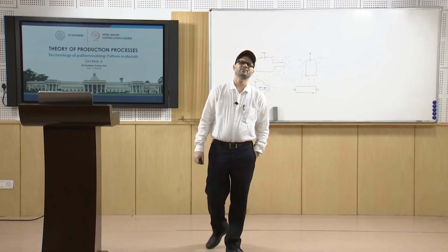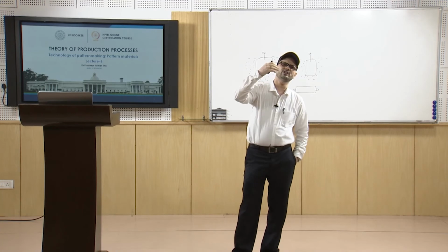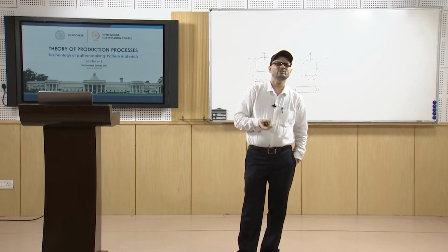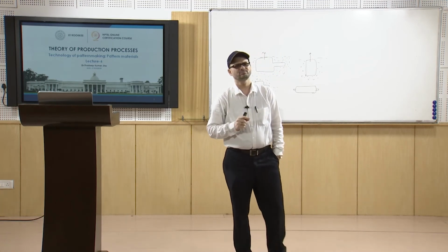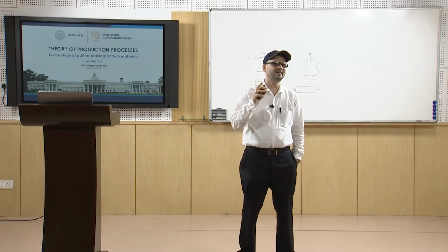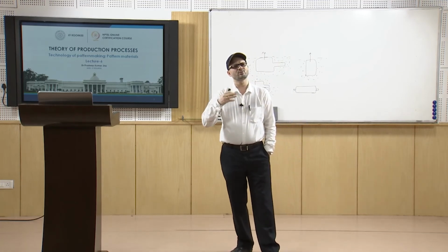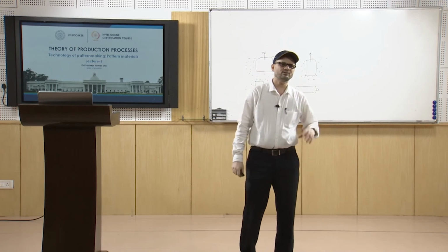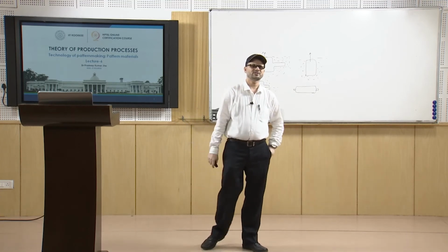Now, you have different materials, like metals as well as alloys. As we discussed, when you need more durability of the material, when you are going to use it for a longer time, then you go for metallic patterns. They are expensive, but they are dimensionally stable and durable. So, you use them when repetitive production of castings is required in larger quantities. That way you prefer this pattern material only in such cases.